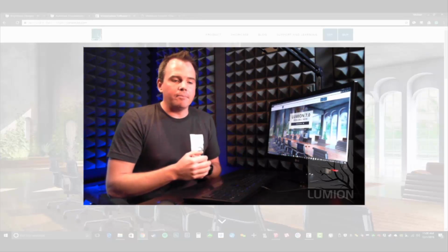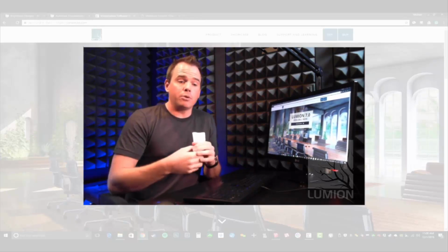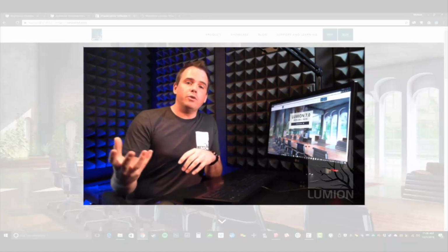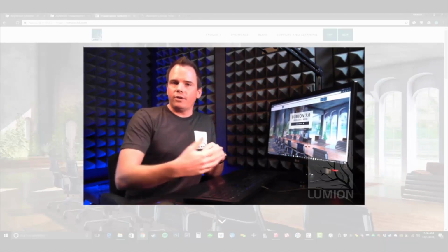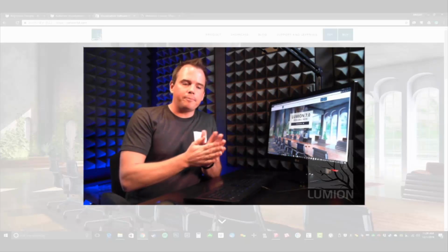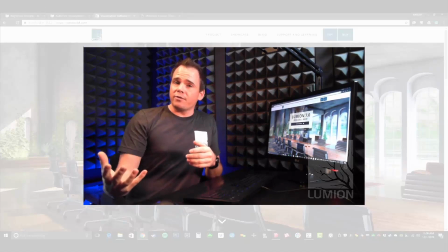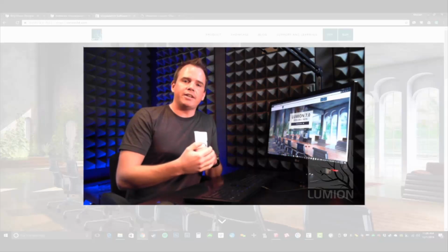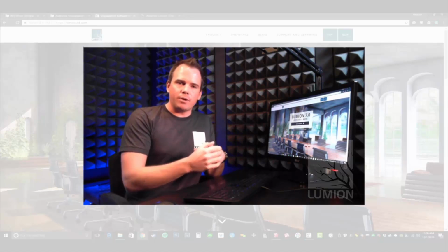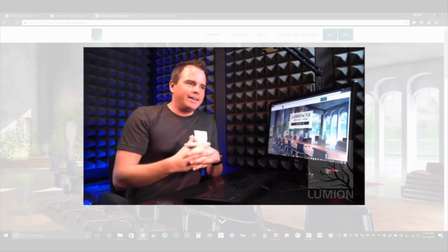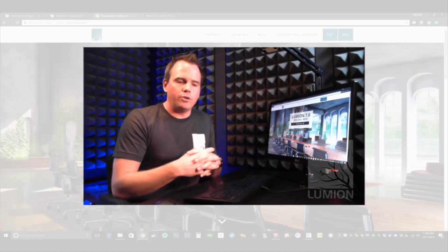Along the lines of materials, we have improved transparencies. We have another new category in curtains, and certainly you can add transparencies to your materials as well. We have subsurface scattering, a new feature in Lumion 7. Basically, waxiness is what we call it. You dial that up, and it gives the surface a kind of glow.